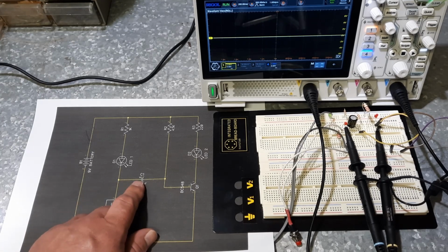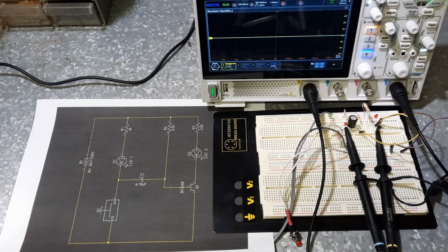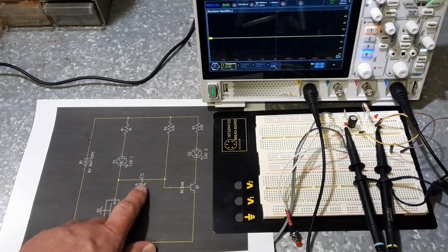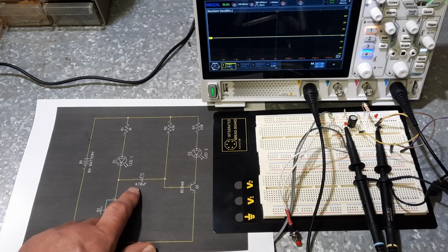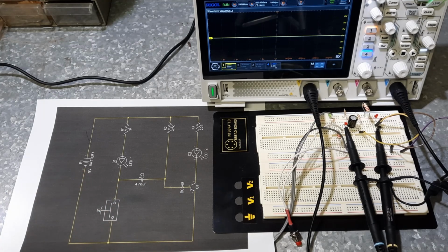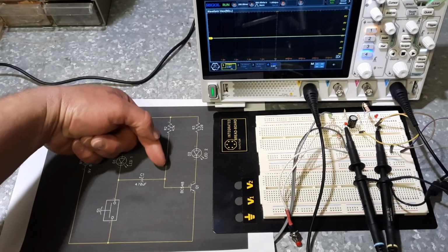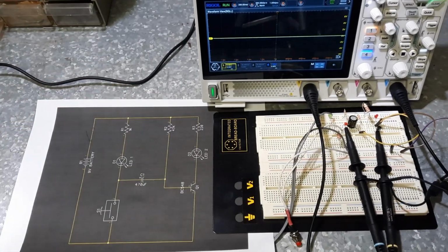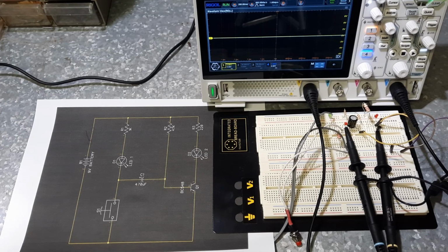This capacitor is charged, we know that. So what's going to happen is this cap, and this is where people go wrong explaining this circuit. I've heard people say this cap will reverse charge. It won't. It can only go one way. It's going to discharge. So this is now going to be at ground potential, and we're going to have a positive voltage coming down here. And you're going to say, but you're reverse polaritying that cap. Yes, we are, but that's what's making it discharge.